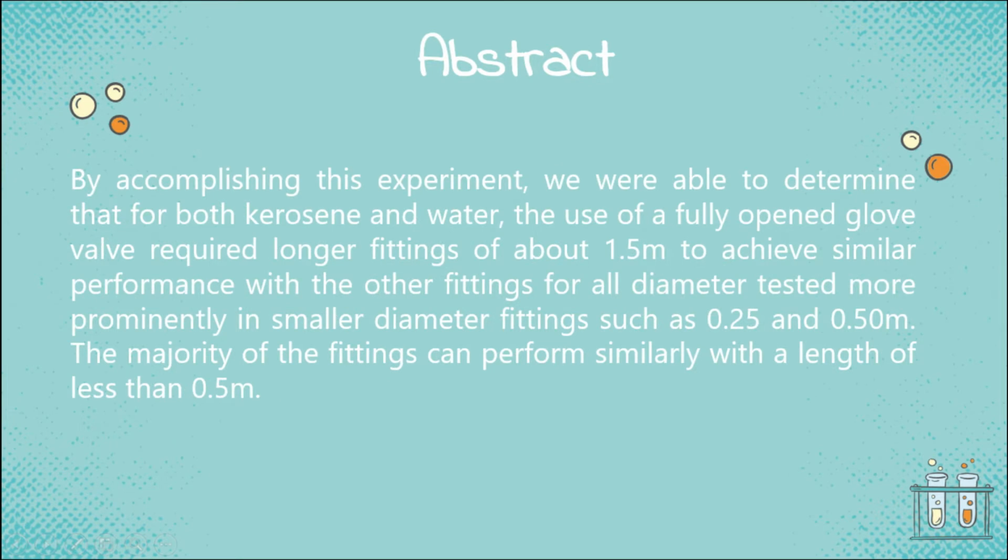By accomplishing this experiment, we were able to determine that for both kerosene and water, the use of a fully open globe valve required longer fittings of about 1.5 meters to achieve similar performance with the other fittings for all diameters tested, more prominently in smaller diameter fittings such as 0.25 and 0.5 inch. The majority of the fittings can perform similarly with a length of less than 0.5 meter.